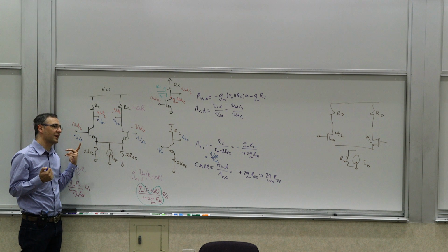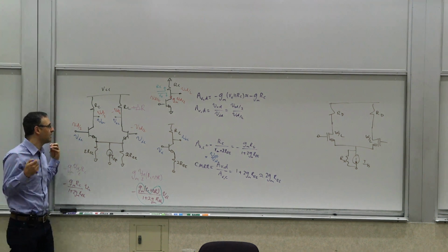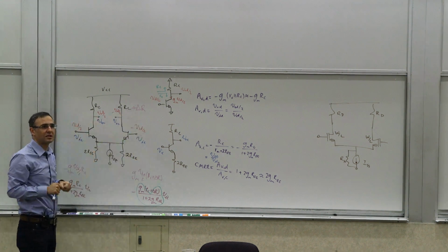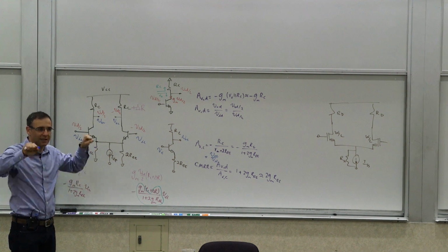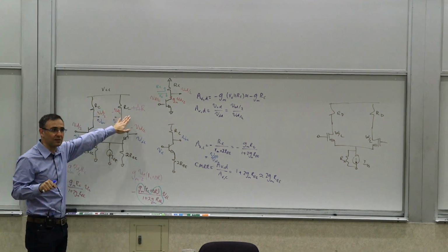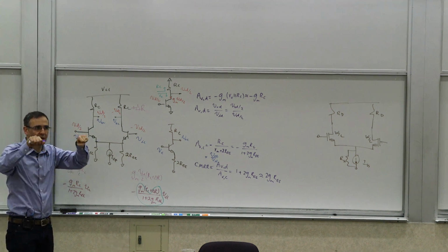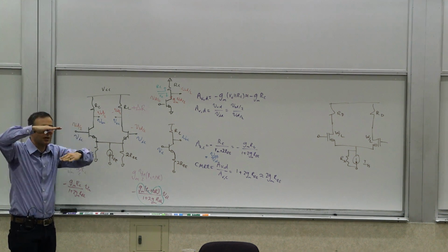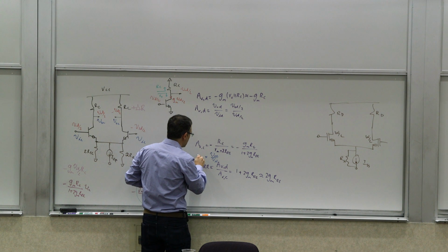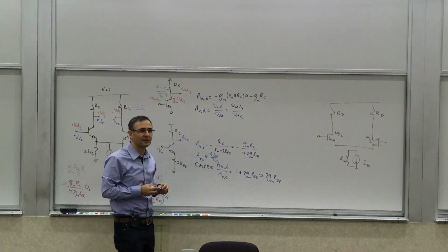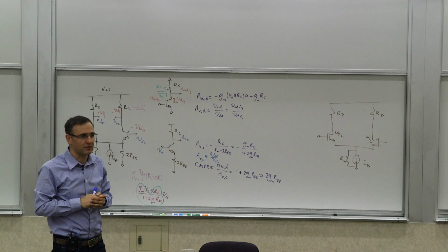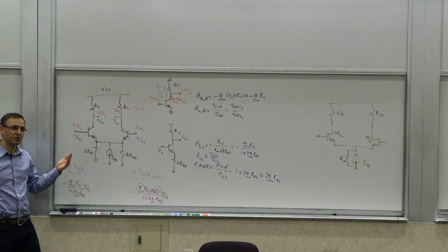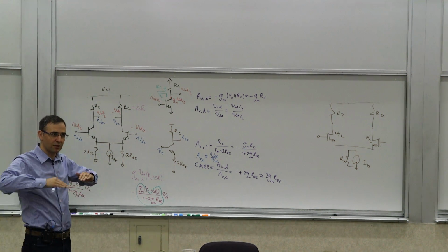No, but for common mode, let's think about what physically we are trying to calculate. We're calculating, if I start wiggling both inputs together, how much fluctuation or wiggling do you see on the output? And if you're doing it together, if the circuit is ideal, if there's no mismatch like this, by symmetry, the outputs need to move together too, right? So it's a question of the ratio of that fluctuation on the outputs that are moving together to the fluctuations on the input, and that's that definition. So this is really the definition of the common mode gain. We define it that way for that physical reason. Now, granted, all of these issues pertaining to mismatch and conversion of the common mode to differential are there. But if you're thinking about purely common mode,